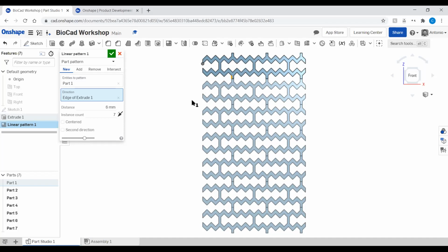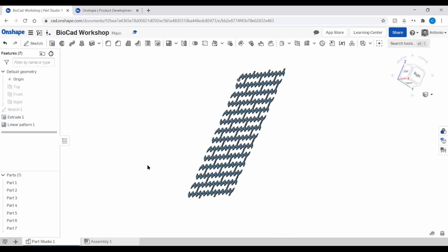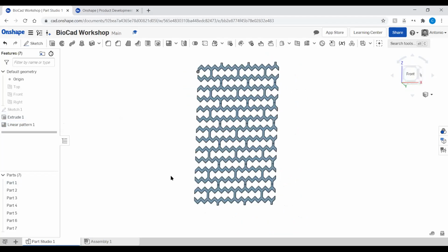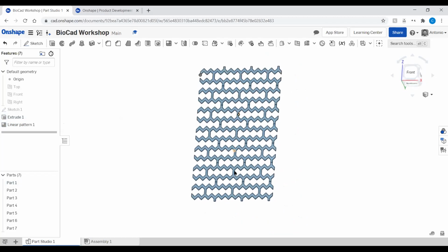Great. So we're almost done. Now that we've got the grid, make sure you click the check mark, and once it processes, you should have this entire grid created in 3D space, which is really great. So now it's just a matter of wrapping it around some cylindrical feature, and as Anusha said, we're going to wrap it this way so that it ends up being a nice cylindrical surface. In SolidWorks or other CAD programs, there's actually a feature that lets you literally bend a planar surface up to a certain degree so that you can bend it into a circle or into some sort of dome.